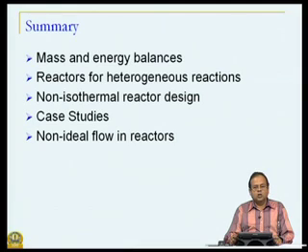One in which there is no energy removal from the system, an adiabatic operation, or the other one where energy removal matches energy generation, thereby maintaining the energy content of the reactor constant, or in short, temperature is constant or fixed, and that is an isothermal operation. So, isothermal and adiabatic operations are two extremes of non-isothermal reactor design.